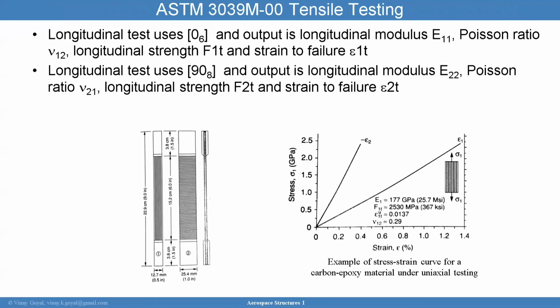So here is how you will measure the modulus in the 0-degree orientation. You apply a load in this direction, and again, I'll be glossing over this because there's a composites course where I go deeper, but I want to make sure you understand the fundamentals here. I apply a tension load to this, and I measure the strain. I put 2 strain gauges, one going that way and one going across. And what I'm showing here is the thickness, but also the width of the sample.